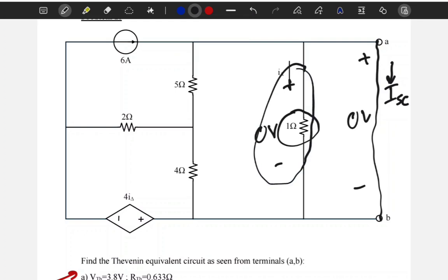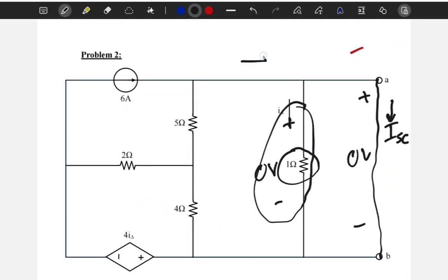Another way to think about it is that if I have a current right here, let's call it I, and let's say it goes into here. Now, would it prefer to go through a resistive branch or a free branch? Remember, current flows through the branch of least resistance, so of course, all of the current is going to go through the branch of AB, this short circuit.